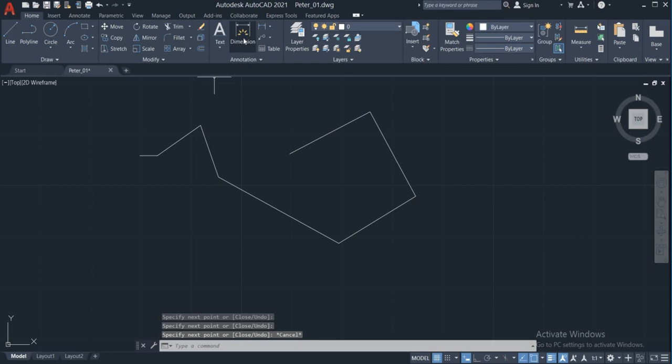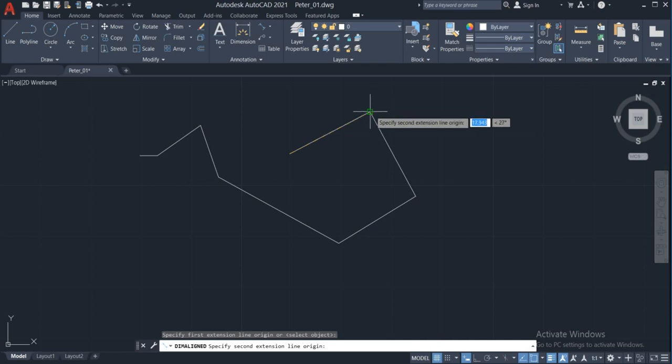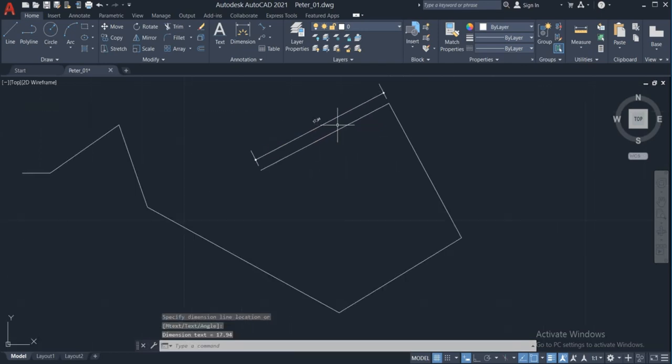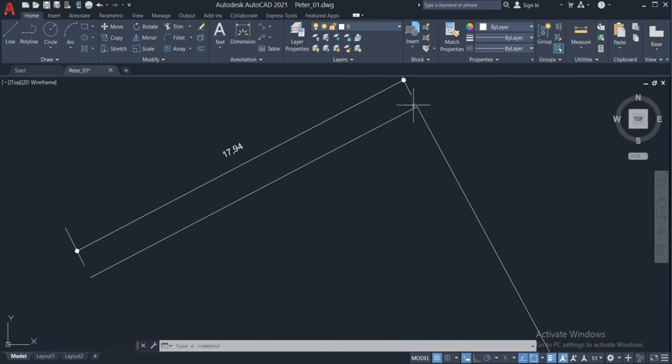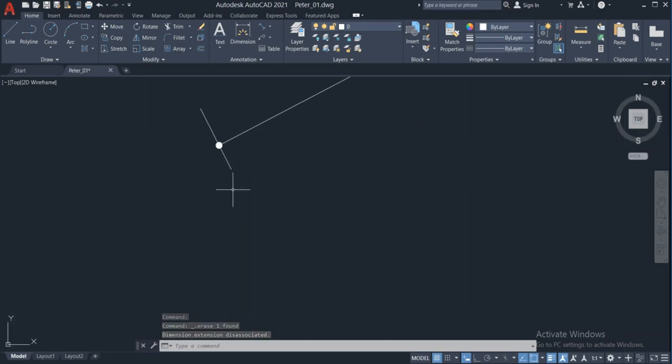But if we put a dimension, any kind of dimension, like a linear dimension, and I start to align the dimension in a much more convenient way, you can put the dimension here and see all the dimensions in the right way. Then another layer is created, called depth points. This depth points layer is related to the points by which you read the dimension. The start point and the end point of the dimensions have small points that you can't see. They are related to the dimension itself. These small dots, if you can see them, are called the depth points. That's why the layer had been created.